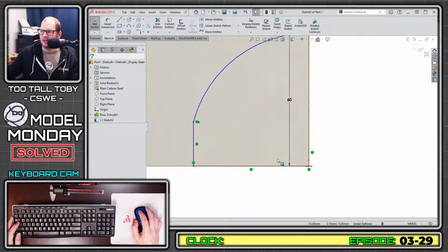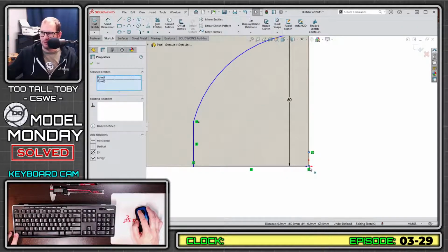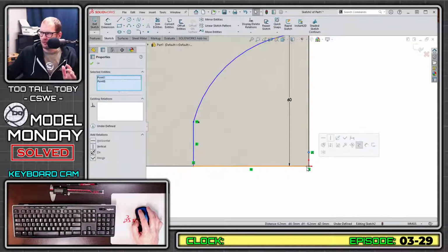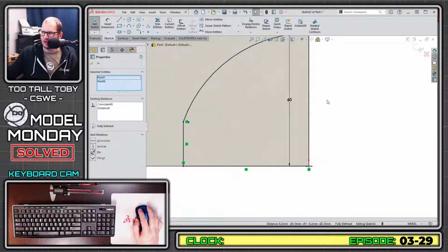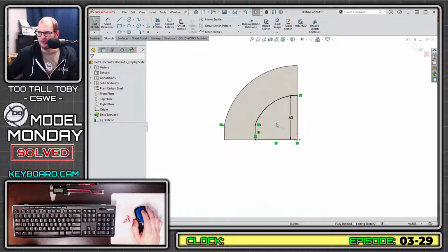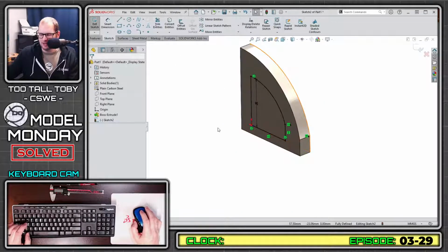Little things like getting comfortable with the idea of pick one, hold Control, pick the other, let go of Control. And then just don't go crazy with your mouse and lose that relationship. Know where that box is going to show up as soon as you let go of Control. It's when you let go of Control that the box shows up. I think actually the name of that Power Move is Letting Go of Control. So if you want to go back and look at that video, it's called Letting Go of CTRL.